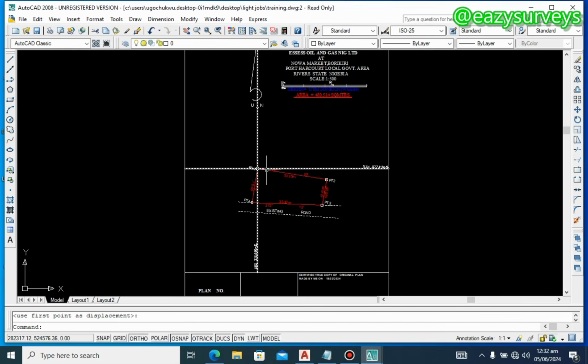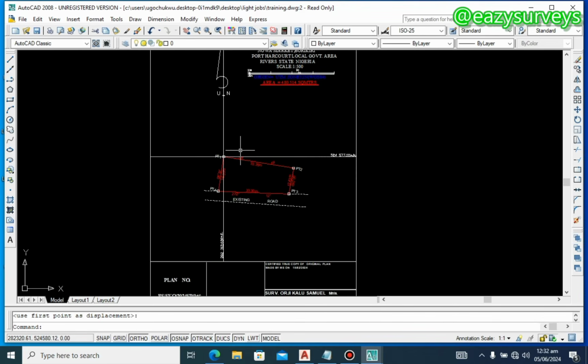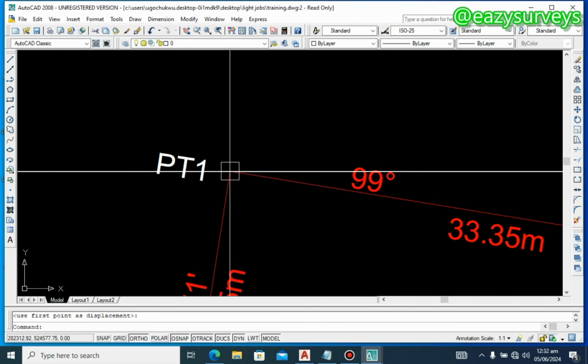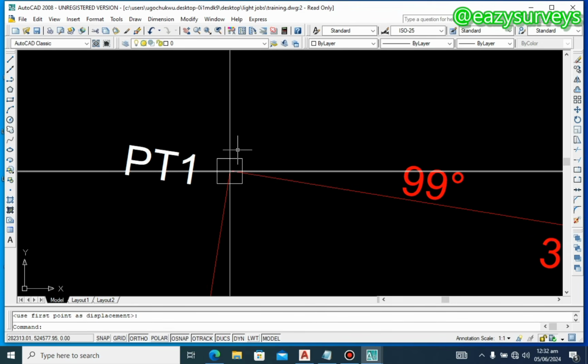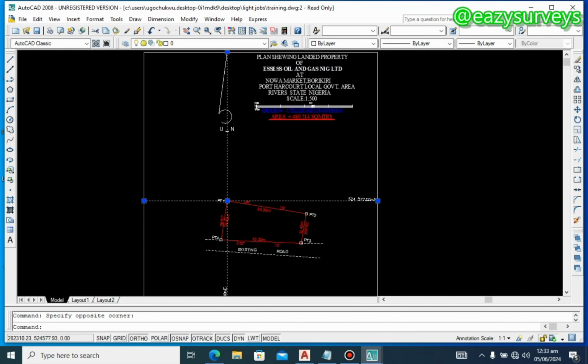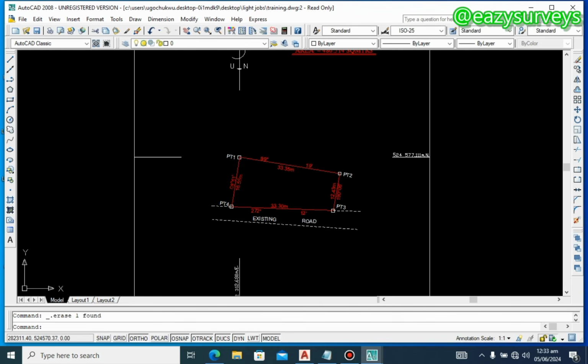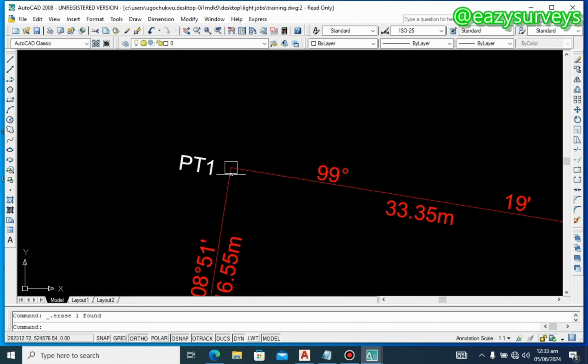So I have successfully aligned the true north and the coordinate to the origin point. I'm just going to delete the polyline I used to align my true north. Then the very last thing is to use the same auto mode, as well as to show the cardinal points.